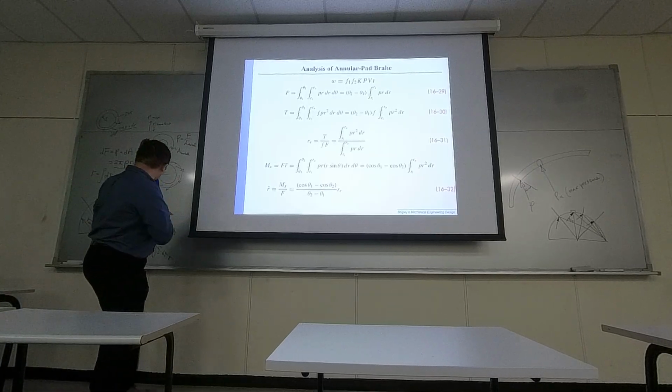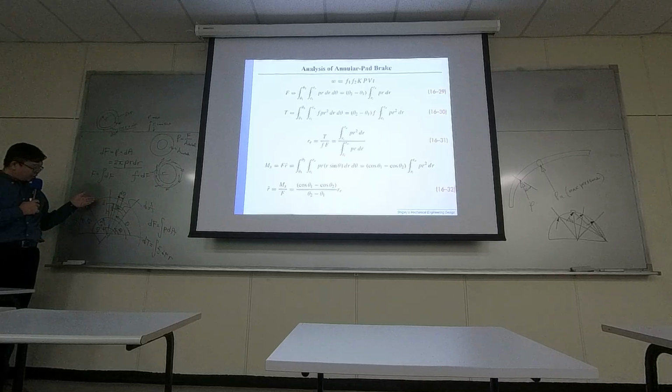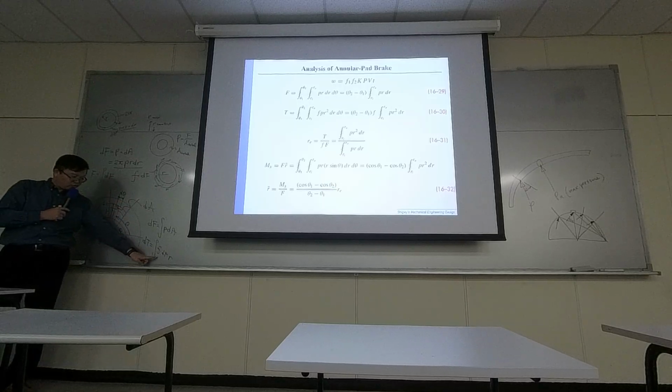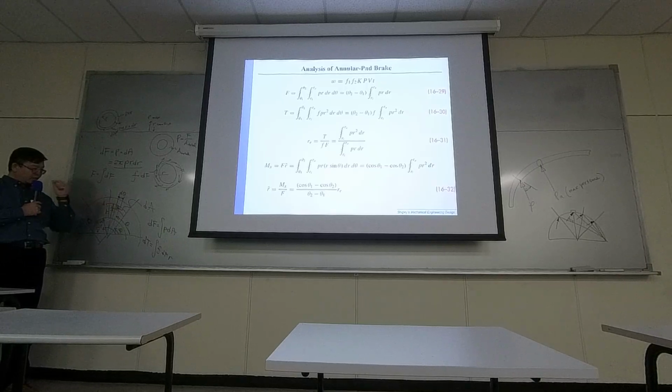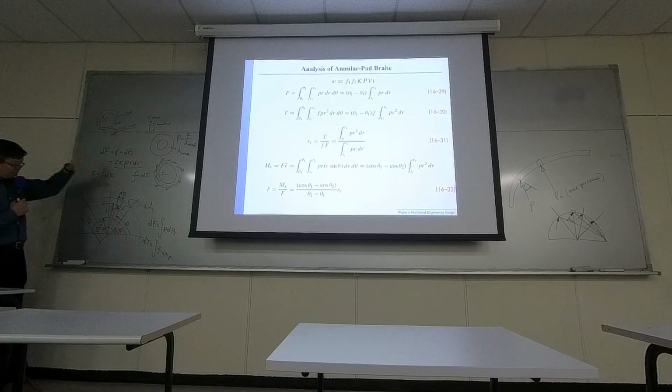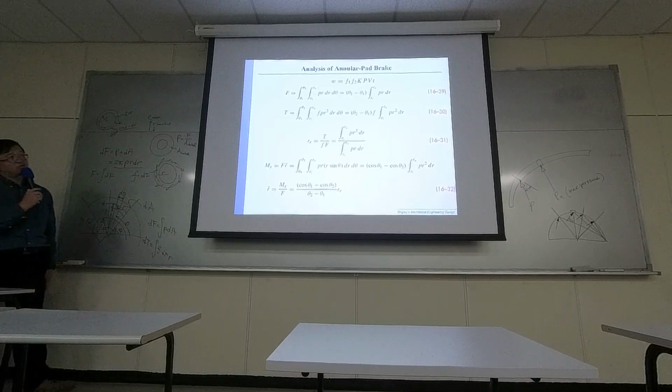Because at this particular point, you have a certain amount of force applied. So your friction force is along the surface, which equals the friction coefficient times the small amount of force. And that friction force multiplied by the radius is the torque contributed by that friction force. So what you are doing, basically, is a complete integral so that you can get the total torque.